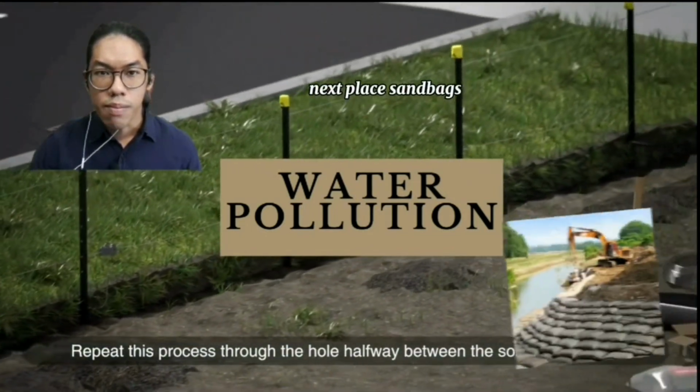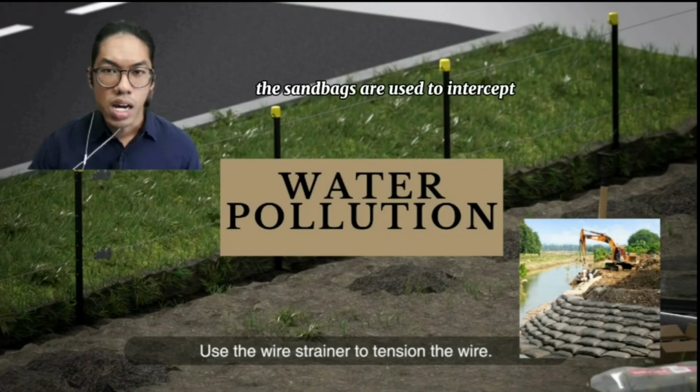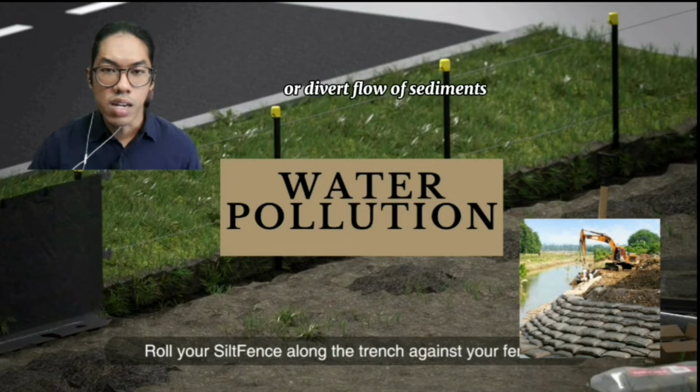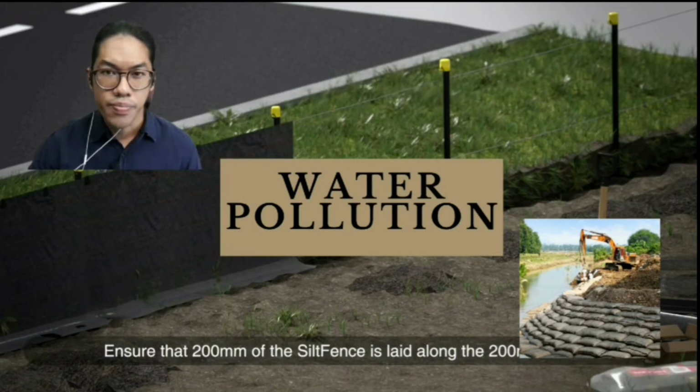Next, place sandbags where the erosion and sedimentation are most likely to occur. The sandbags are used to intercept or divert flow of sediments. It is a viable method due to low cost and ease of construction.